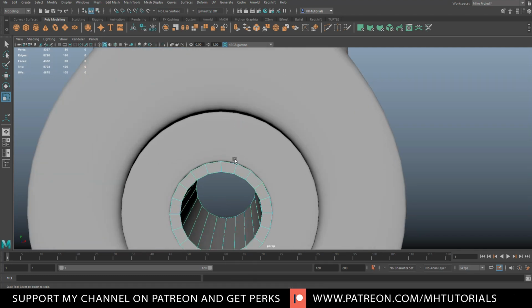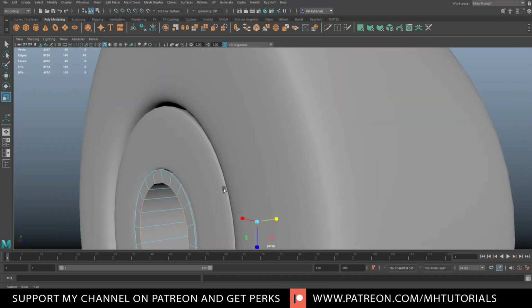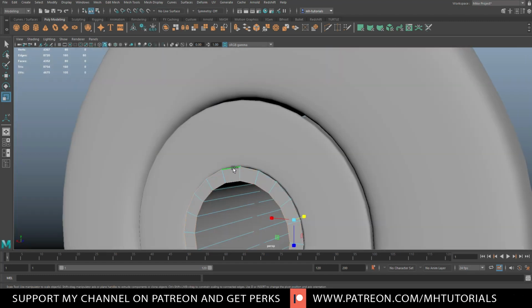So we're going to go into Edge, double click, Shift, double click, Shift, double click, and Shift, double click. Bevel that, 0.01, hit Enter. Segments, no need for that. Let's try 3 again. Yeah, it looks fine.